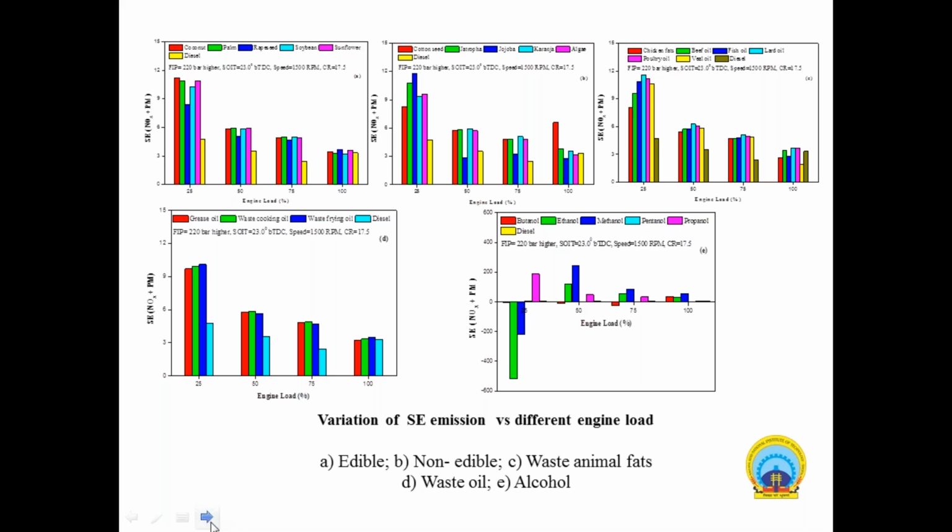Studies say up to a maximum of 20% biodiesel we can use directly in our engine without any modification. After 20%, if the biodiesel percentage is more than 30 or 40%, we can do some modification in the engine. So now the studies say the maximum or optimized value is B20. So these all are related. These results I have shown only for the emission part, and with the help of Diesel-RK we are doing these results.